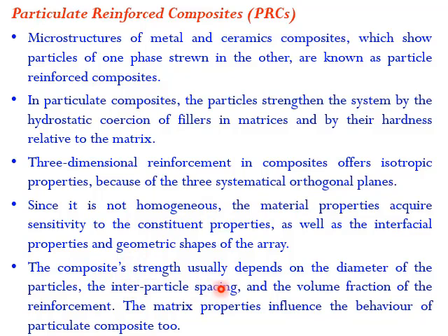So the composite strength usually depends on the diameter of the particle, the interparticle spacing, and the volume fraction of the reinforcement, and the matrix property influences the behavior of a particulate composite material, because the binding of these particles intact is the property of the matrix material.